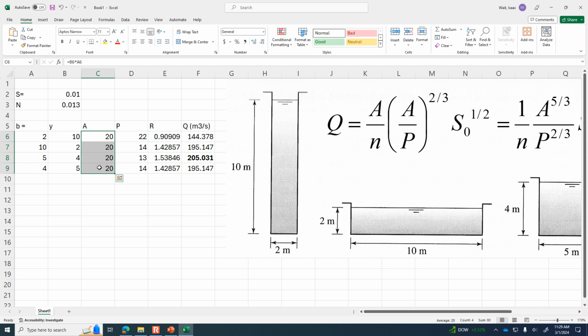If we have the width as 6.32 meters and the depth as 3.16 meters, you can see that the area is real close to 20. This wetted perimeter is less than the smallest one we've seen so far. So that gives us an idea we're on track to have the maximum flow capacity. And sure enough, that calculated flow rate is greater than the previous maximum that we saw. So we'd call this the best section, or the most efficient.